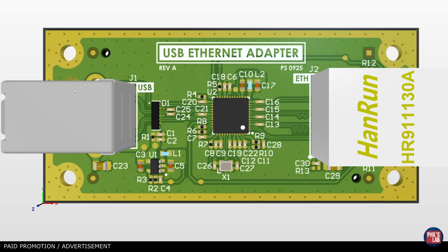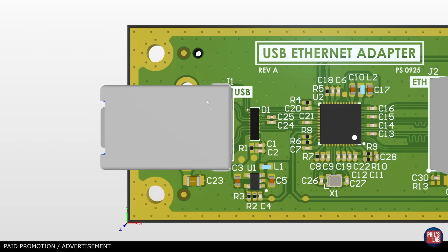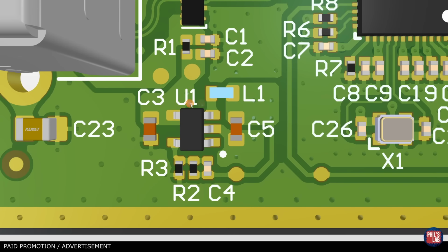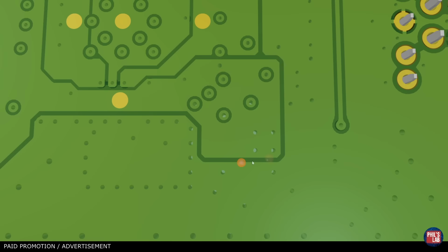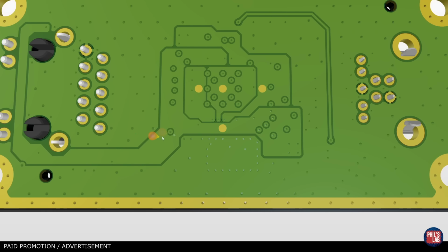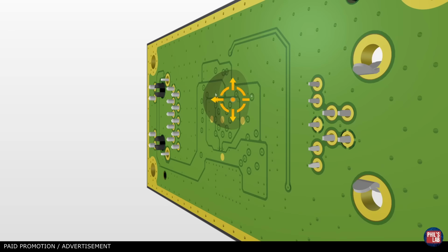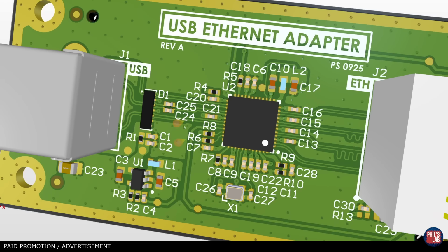Our original power source is from the USB, so from the host device that connects to this USB Type B jack on the left-hand side. We have a simple 3.3 volt step-down or switching buck regulator that generates our 3.3 volt rail. At the output LC filter, we have 4 vias via this little planelet that feed onto the bottom layer, and that distributes this 3.3 volt rail and 3.3 volt net throughout the PCB. And again, we go with some vias to the top of the board again through our decoupling capacitors into our physical layer. So that's what we're going to be performing the DC drop analysis on.